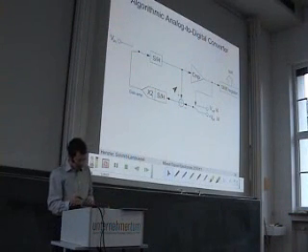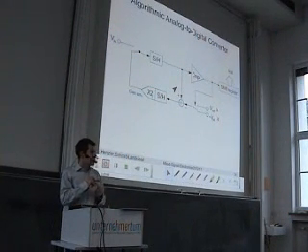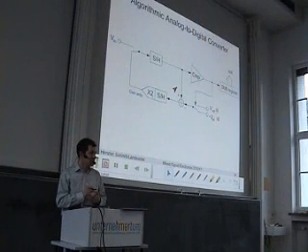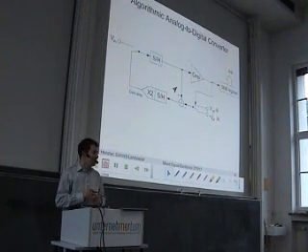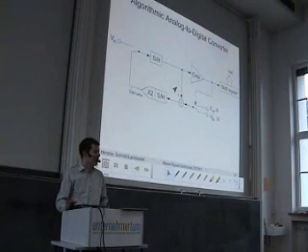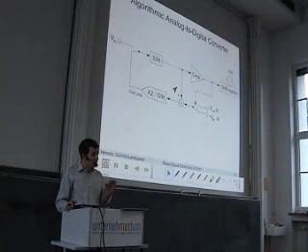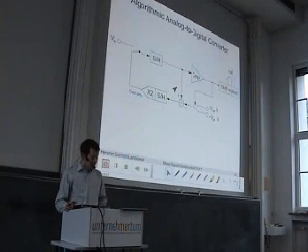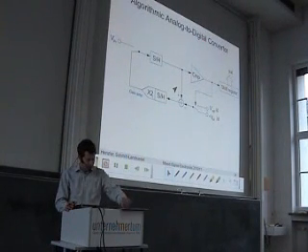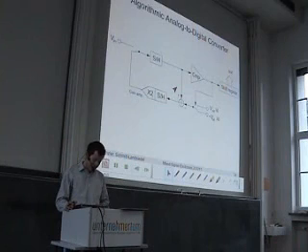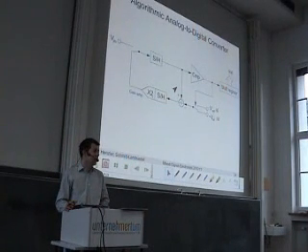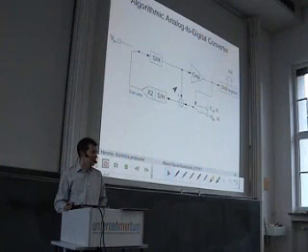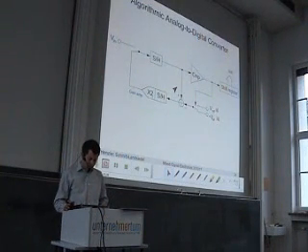And we will see next week that it is very important that the threshold of the comparator is precise, and it is also very important that the gain factor x2 is precise, that it is not 1.9 or 2.1, but it is exactly 2. And therefore a good thing to do is to do this amplification with switched capacitor circuits, due to all this robustness against component variations that we have discussed.